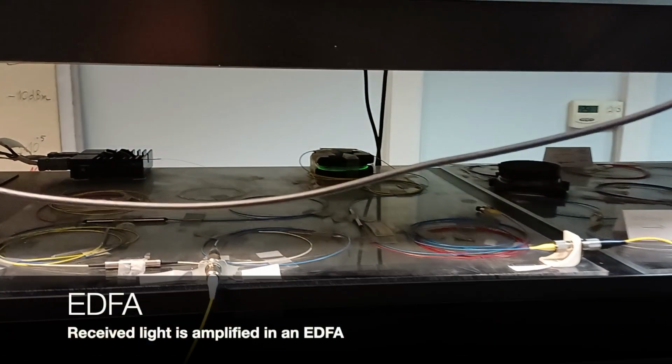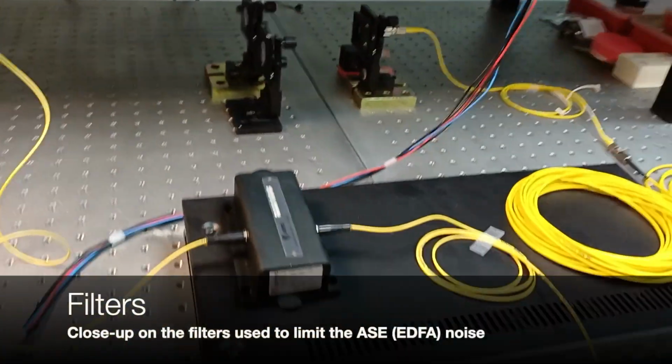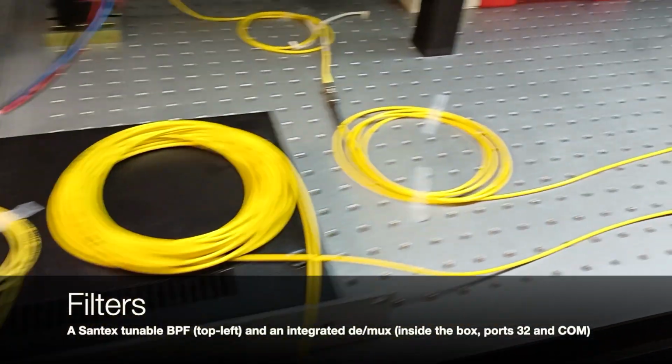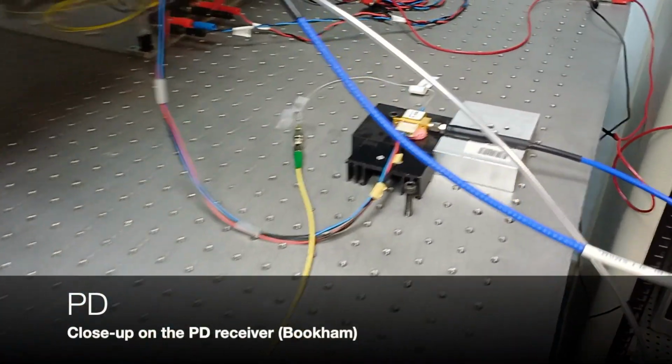Received light is amplified in an EDFA. Notice the characteristic green-lit EDF spool. We close up on the filters used to limit the ASE EDFA noise. We close up on the photodiode receiver.